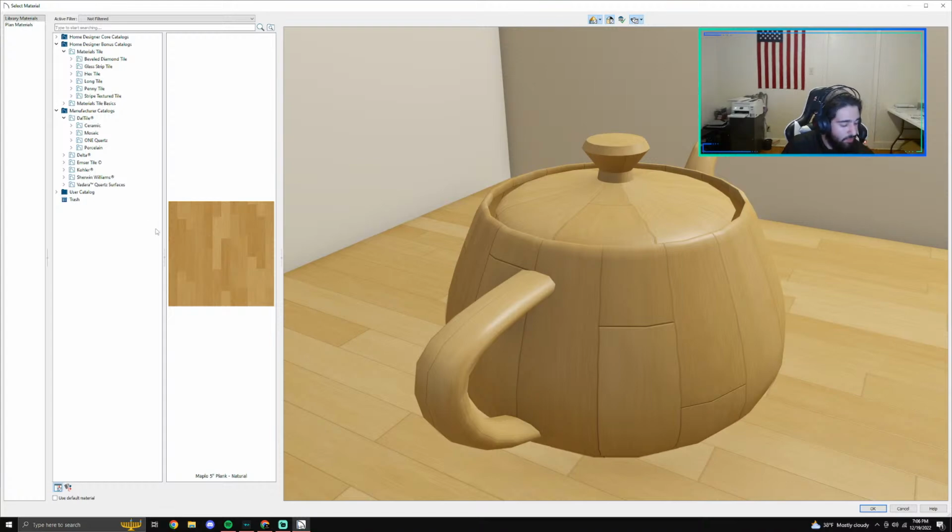The new build. So I actually know this guy. He's a mason for the house I built on the weekends. So he's getting a little more slack on this pricing. But what I'm doing, he doesn't know what tile he wants. He wants to change out the pans that are there. The plumber put in the standard vinyl pan, and he did it wrong because where the curb meets the floor, there's like this really wide radius, so I can't get my mud bed in there. So we're gonna cut it out and put a membrane bed in there.